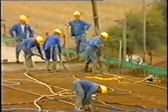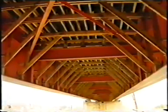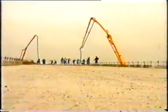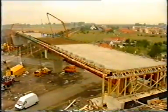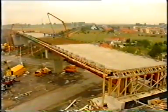In a composite structure, formwork is needed during erection. When the concrete deck has reached sufficient rigidity, this formwork may be removed and the deck acts as a rigid plate. The lateral forces are mainly transmitted to the end cross girders and then to the supports.